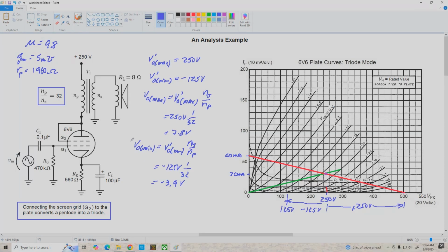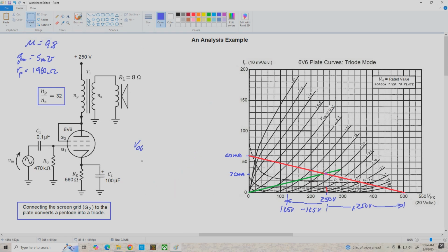All right, next, let's determine the voltage gain. So let me clear off the workspace. And we'll start by determining the gain of the tube at the plate with respect to the grid. That is, A'V equals gm times r'P, but I'm going to put a prime on the voltage gain as well because that's the gain of the tube, not necessarily the overall gain of the amplifier.